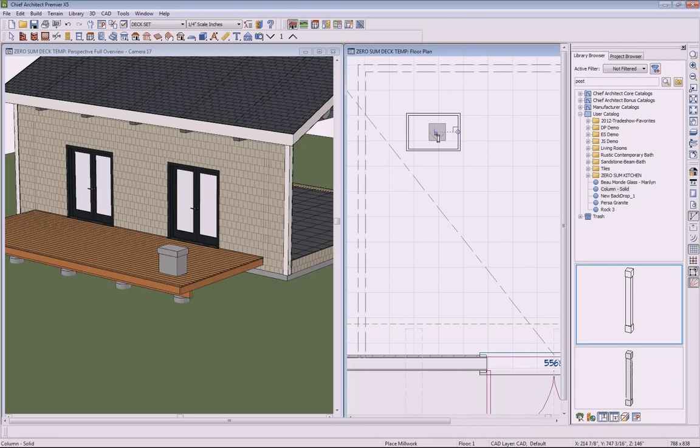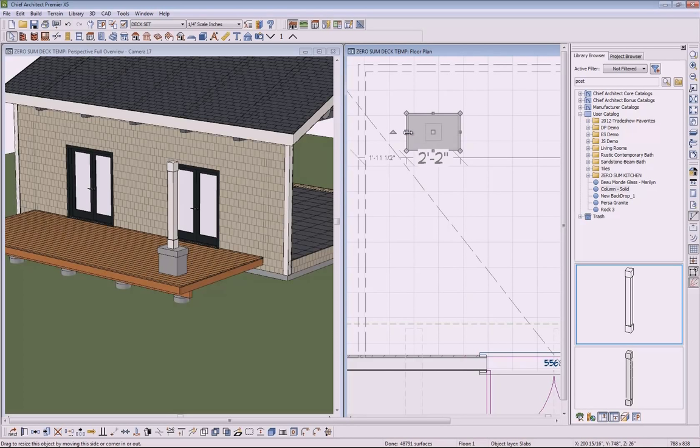We'll just select that post, drop it into place, and of course if you want to center that, we can select it in our center objects and grab the center of that capstone or column base, and then with it selected again, center it both ways, so then you know that's precisely located in the middle. So we have our post created here, and it's looking pretty good, just about exactly what I'm after.